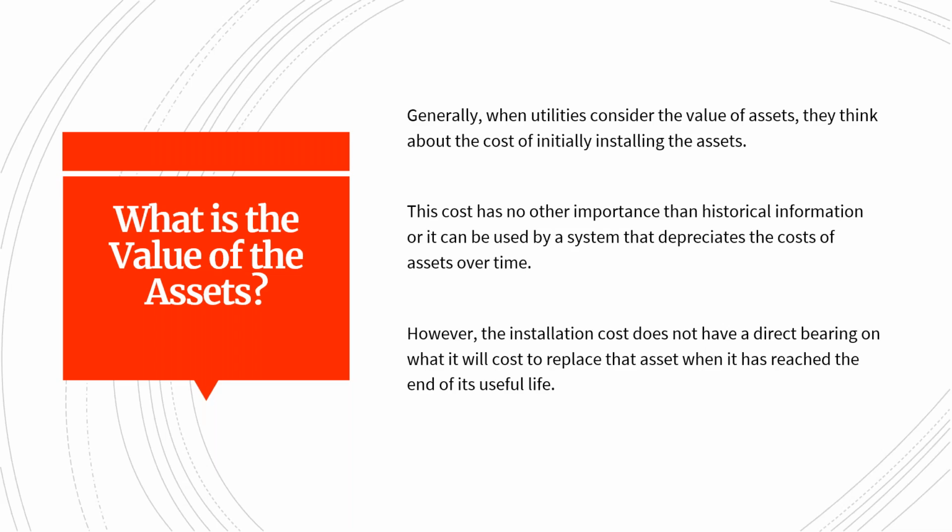Some prices may increase, such as materials, while technological advances may decrease other costs. The real value of the assets is the cost it would be to replace the assets using the technology the system would employ to replace them. If the system has asbestos cement pipe now, but would replace the system with PVC pipe, the real value of the asset is the cost of replacement using PVC and the installation cost associated with PVC.